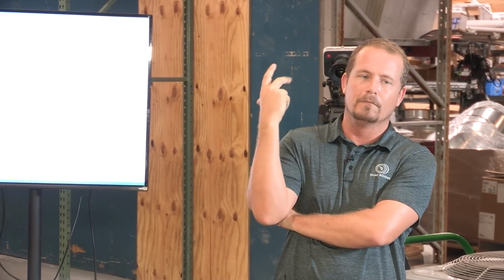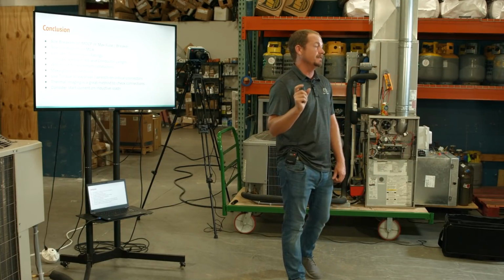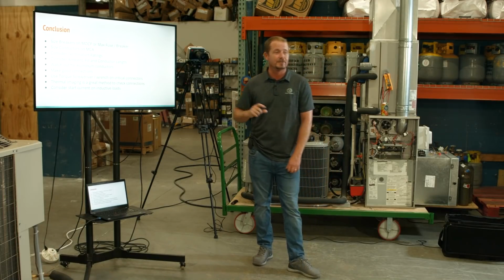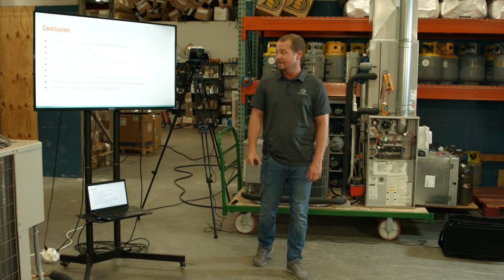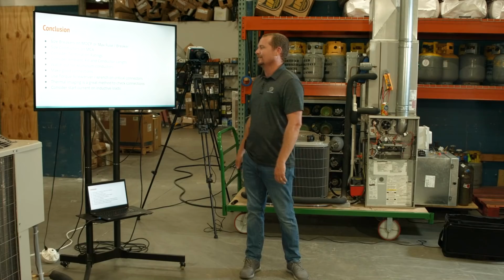But in more mission critical environments like industrial, heavy commercial, where you need things to run in very vibration heavy, high temperature environments, using a torque screwdriver and a torque wrench to make all of your connections is a good idea. Also keep in mind, do not confuse inch pounds with foot pounds, because you will really break some stuff off if you try to set it to 22 foot pounds rather than 22 inch pounds. Also, in reverse, it will be very loose.